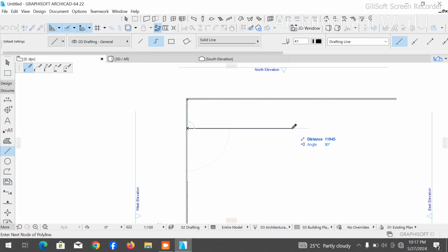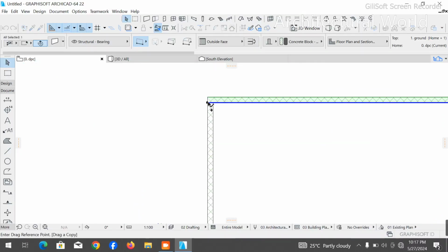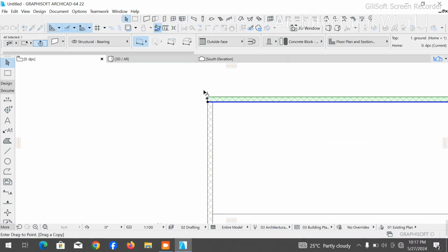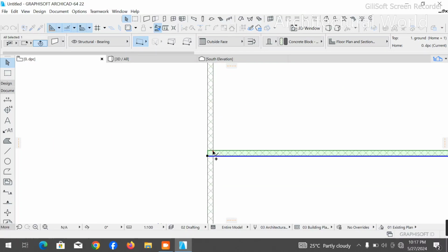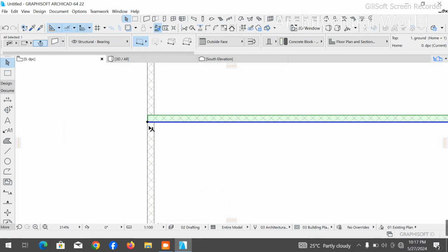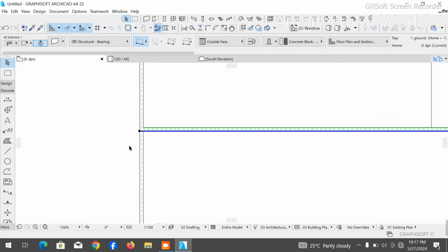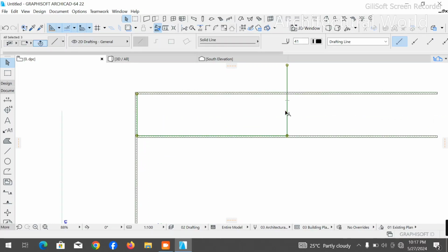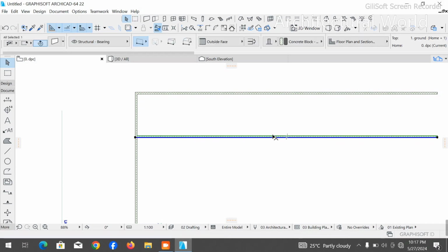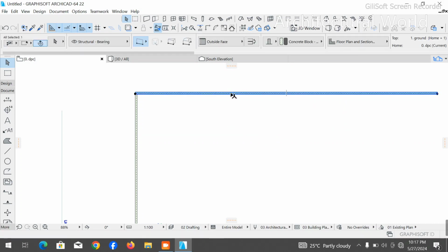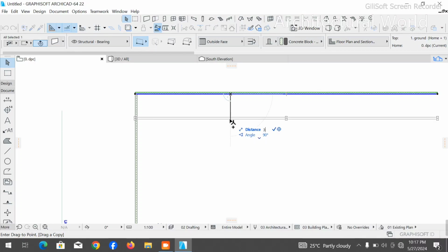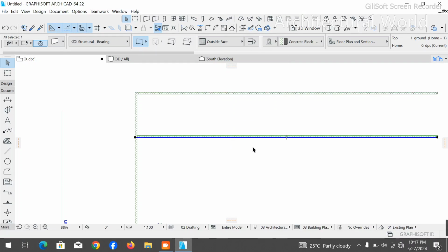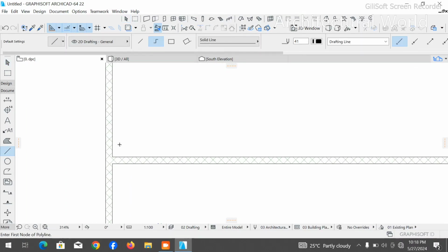You just have to drop the line anyway, then create a duplicate wall like this and paste it here. So you can see on this, you don't need to add a block wall because it's added automatically. But in case you think this method is stressful, you could just pick this, press your Control D, and since you are looking for 3.3 meter, all you need to do is just add 150 millimeter to it. That's 3,450, and that is 3.3 meter. Let's check it at the end. Let's check it.